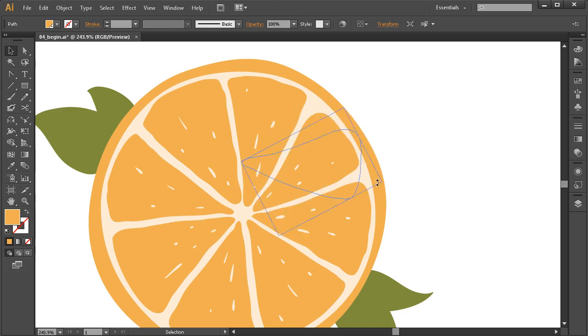Now, the same keyboard shortcuts apply to rotating an object. If I hold down the Shift key and do that, you're going to notice that something a little different happens. Instead of scaling or transforming the object, we're locking the rotation to 45-degree increments. I can hold down Shift, and you can see it's ticking around at 45-degree increments.